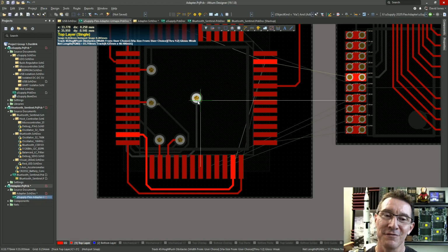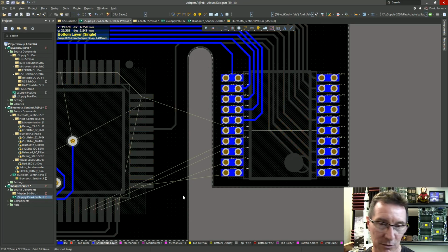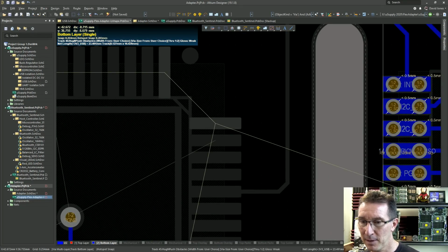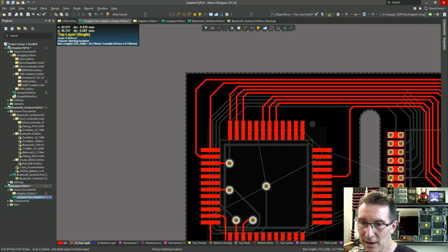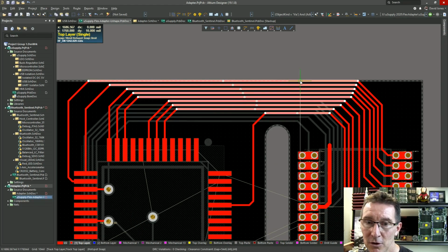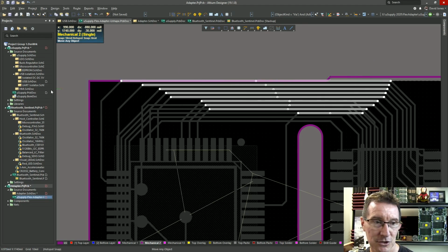Once again, you could leave it till later and then try and flood fill your way out of your routing problem, but let me just get the other traces around and we'll see what's what. This is where I could actually go to the top layer, for power and ground here. You could argue that you could maybe route the top layer out like this and around, and push all those traces up. You could argue that I could even move it one more like that, extend my board out. This is what you can do when your constraints aren't really major constraints.